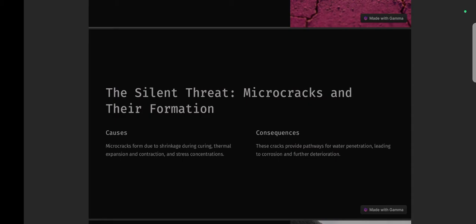leading to deterioration. Corrosion of reinforcement: microcracks near reinforcement can allow moisture and oxygen to reach the steel, increasing the likelihood of corrosion. The expansion of rust from corroding steel can exacerbate the microcracks and eventually cause larger cracks and spalling.